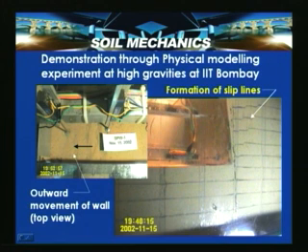And this is the passive side, because the wall movements are not adequate. So the passive state of plastic equilibrium was not observed here, but you can see the active state with a movement or rotation about the top portion. You can see a series of rupture planes, which shows the evidence of what we are discussing in these lectures.